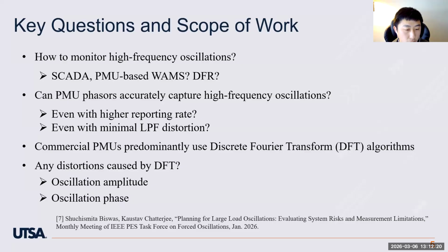It's very efficient computation-wise. It's well understood and standardized. It aligns very well with the IEEE C37.118 performance requirement. So in short, historically and practically, the DFT-based phasor estimation is the industry standard.